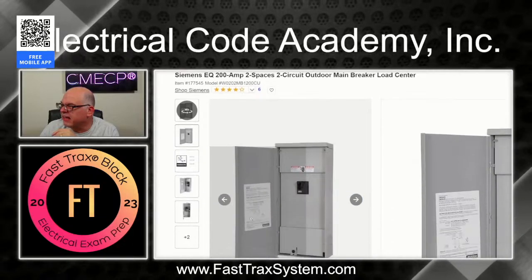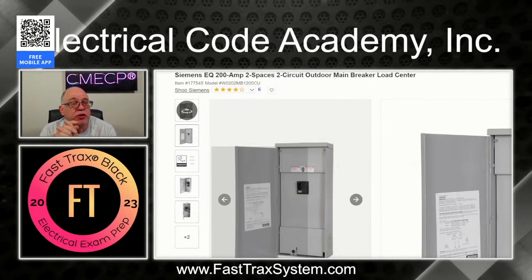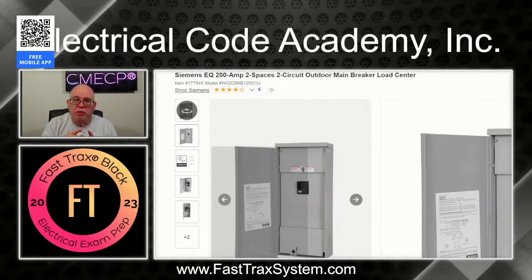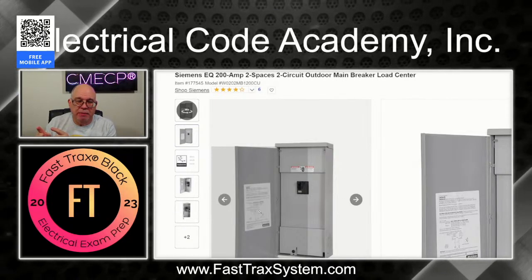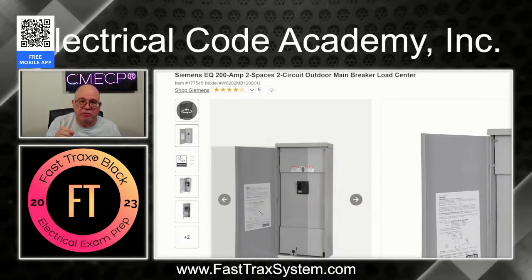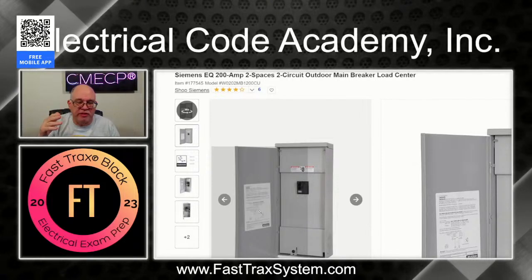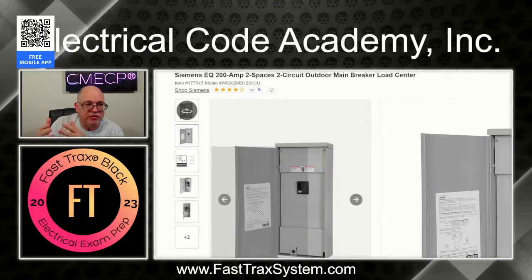And you really can't see the label, but on this label, it says suitable for use as service equipment. But there's something important about it. It does not say on it suitable for use only as service equipment, because it has the ability to remove the main bonding jumper, that connection to the grounded conductor, right? So that's important. We'll see that a little bit later when we're talking about the different options for disconnect. So this is the first one. This is what I would use as a service disconnect for me.